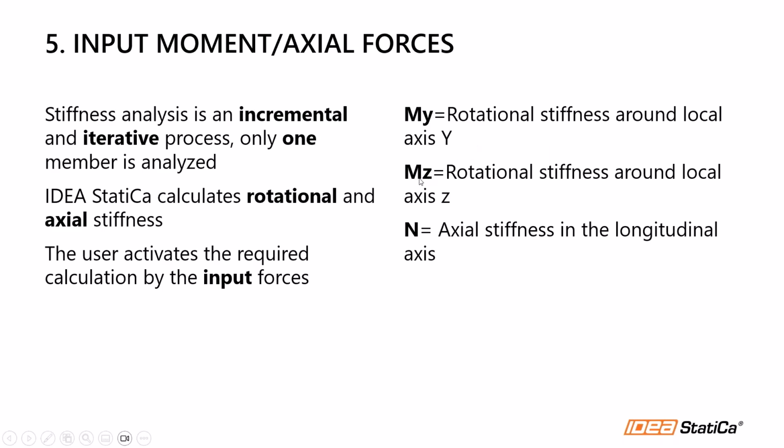And if you input a force on MC in the loads table, then you tell the software that you want to calculate the rotational stiffness around the local C axis. And the same for the axial stiffness. So IDEA StatiCa can calculate rotational and axial stiffness. If you want to calculate the axial stiffness, just put an axial force in the member. All right, that's the way we activate these calculations.